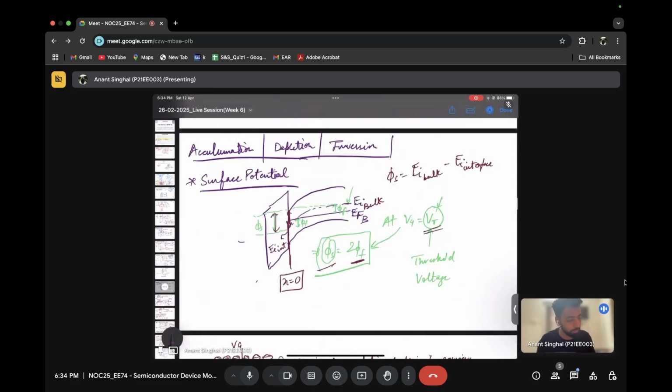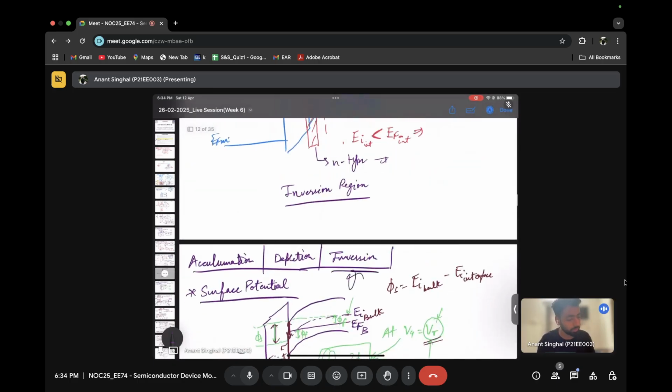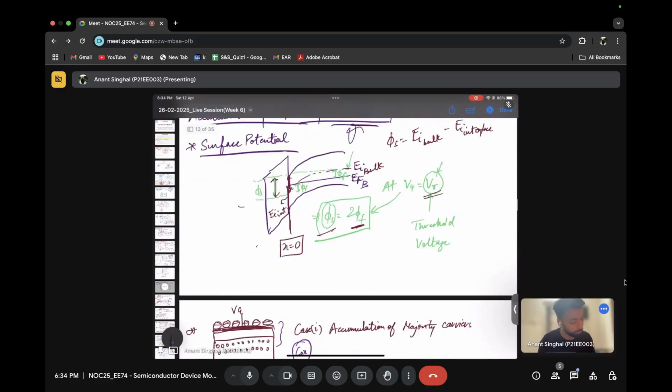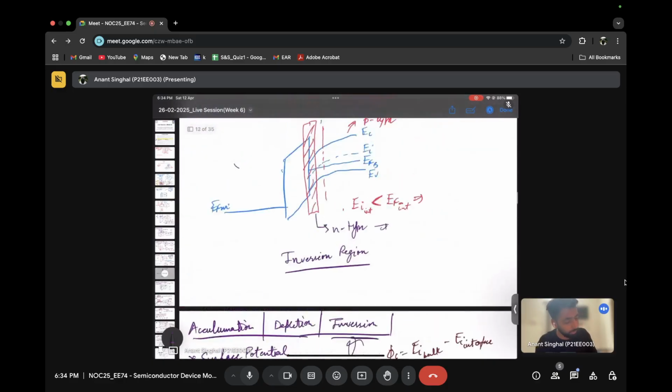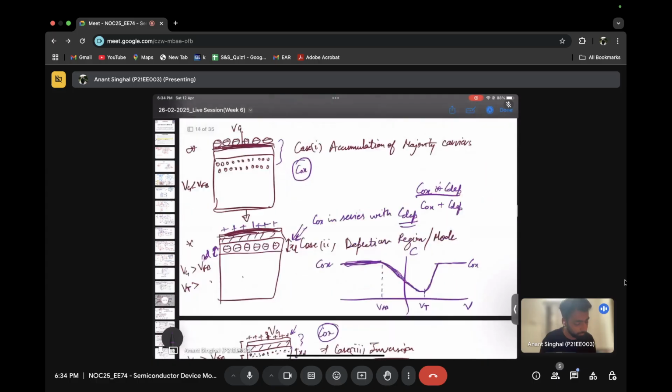And then a very high voltage will lead to the inversion, that is, more electrons will come out. From this band diagram, we came to know that for the p-type substrate, here you see the Fermi level is lower than that of the intrinsic. But once we apply a certain voltage, sorry, this intrinsic level is now down below the Fermi level. So this is what an inversion of the semiconductor is. It became N type from P type. So that is how that CV looked like this.